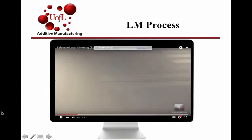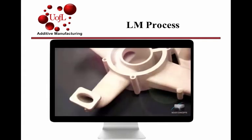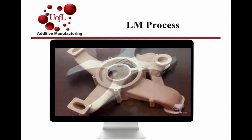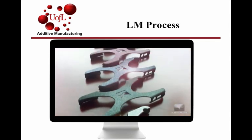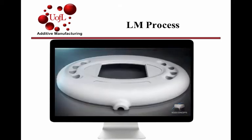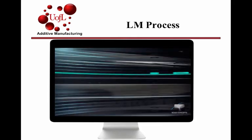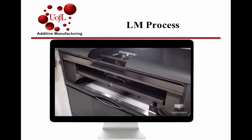Let's start out with an overview of the process itself with this short video. SLS is an additive manufacturing technology that uses powdered nylon 11, nylon 12, and PEEK materials. Parts produced are lightweight, highly durable, and both heat and chemical resistant, making SLS an excellent choice for producing production parts without the expense of tooling. The SLS process begins by splitting 3D CAD data into thin cross-sections or layers. The data is then transferred to the SLS additive manufacturing equipment.